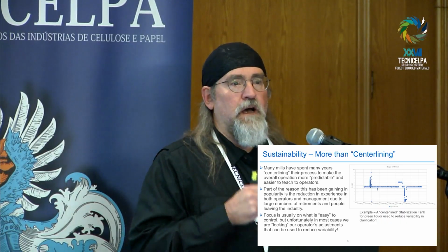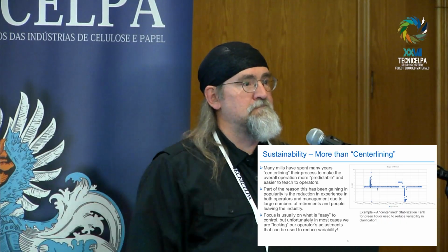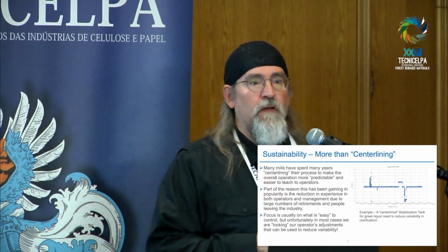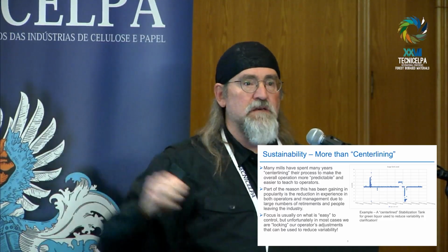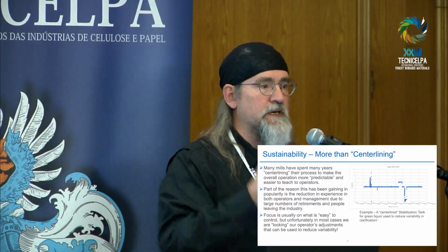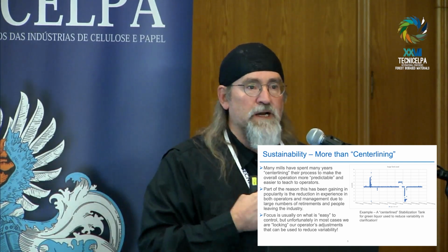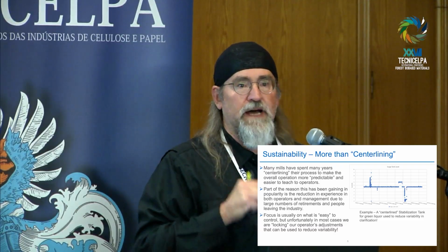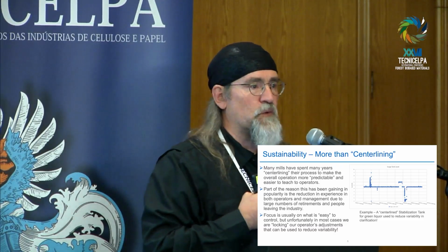Okay? How many of you have perfect wood every day? I've never seen it. I quit fighting about it, okay? But if I now center line the rest of my mill to be flat and I have a variable raw material, guess what? The end result is variable. I don't want to be center lined. I want to center line on key variables, not the little variables, not what's easy, okay? So this is what I'm talking about.